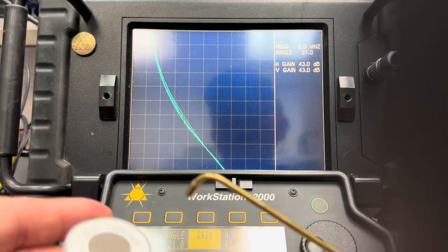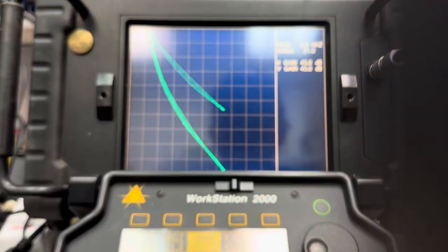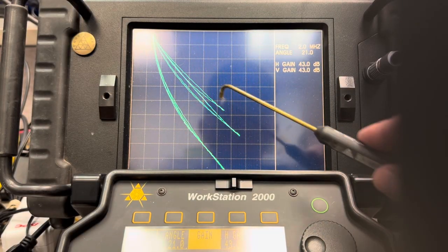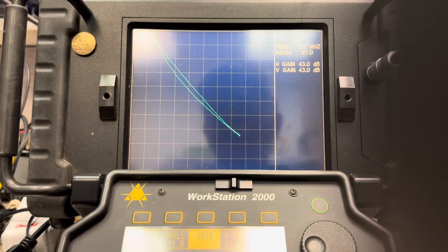So this is titanium, 1.09% IACS. Okay, that's up there a ways. And then I'll use 304 stainless. You're not going to have any trouble telling that material from that material. 304 stainless, titanium. They're not that far apart, but they're a lot farther apart than the silver and the copper.